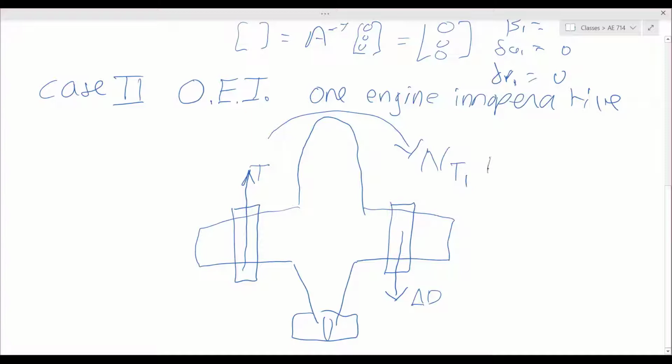So really what he has is a total value here. This is the yawing moment due to the thrust happening on the left side, and this is the yawing moment due to the extra drag of the right side. In the book, he has some ways that you can estimate this for an airplane when you're doing preliminary design. He gives this formula.